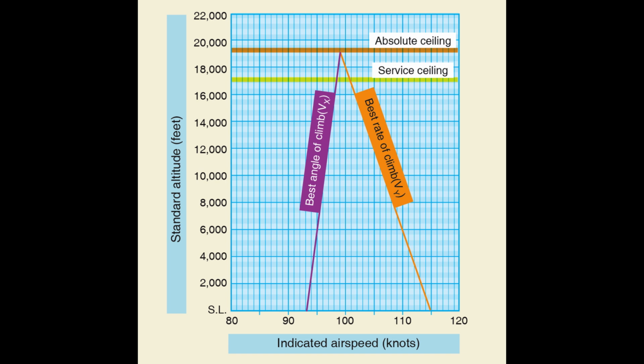The pilot should understand propeller effects during a climb and when using high power settings. The propeller in most airplanes rotates clockwise when seen from the pilot's position. As pitch attitude is increased, the center of thrust from the propeller moves to the right and becomes asymmetrical. This asymmetric condition is often called P-factor. This is the result of the increased AOA of the descending propeller blade, which is the right side of the propeller disc when seen from the flight deck.